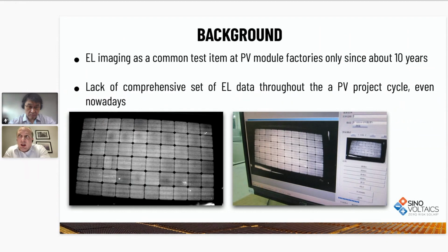Now, it's only been roughly 10 years that EL imaging has increasingly become a standard, or let's say a pretty common quality control item during mass production of PV modules at almost any module assembly line, unlike in the earlier days, when even at the factories the focus was more on visual inspection and IV measurement and some electrical safety checks here and there only.